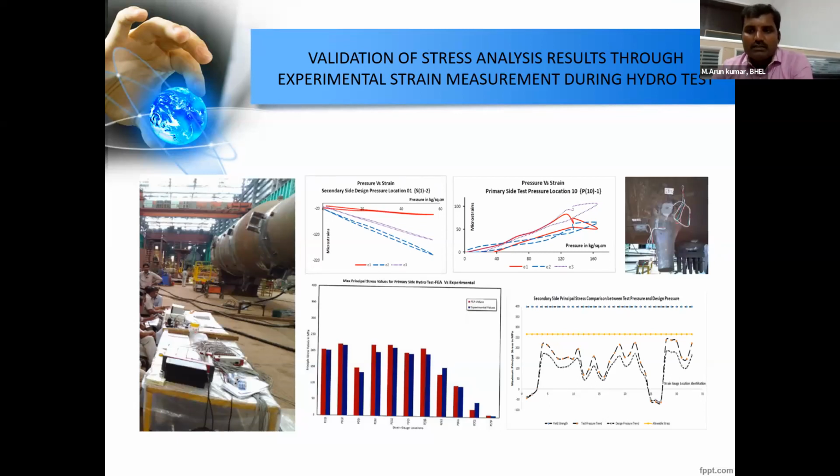In case of our steam generator, we have around 2500, exactly 2489, U tubes. So there are 5000 holes in the tube sheet. For example, if we over design even 1 mm thickness of tube sheet, what happens?